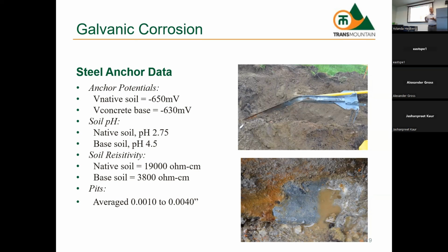Magnesium anodes don't last longer than 20 years. When you design this system, you would say, hey, I need to get at least 15 years out of this. So you could leave it for 5 years and then check it at 10 years if it's not regulated. But you run the risk of it failing prematurely if you don't know about it. Yeah. Okay.